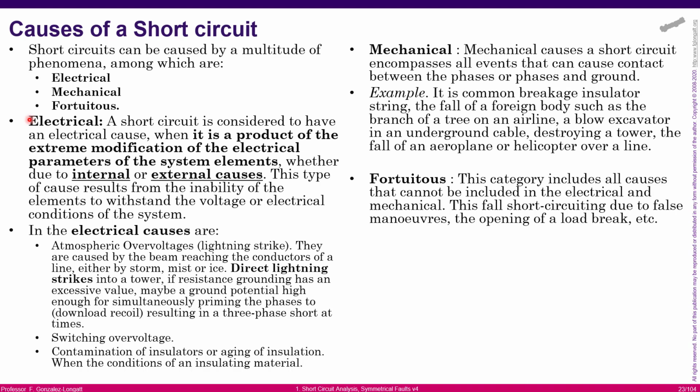The insulation can be affected by many reasons, especially overvoltages coming from atmospheric overvoltages, lightning strikes, or coming from internal overvoltages from switching or circuit opening operations, okay?